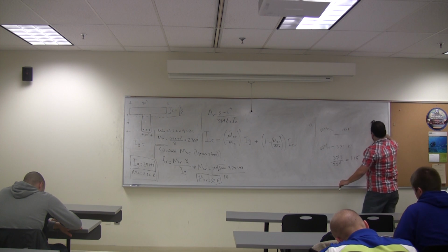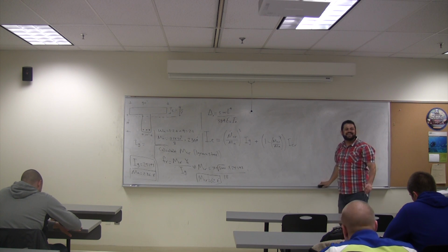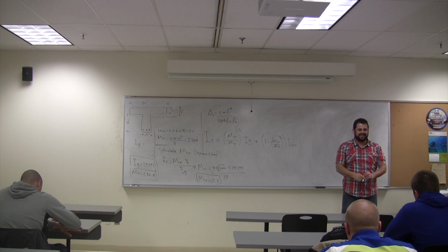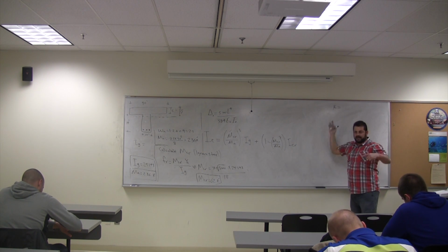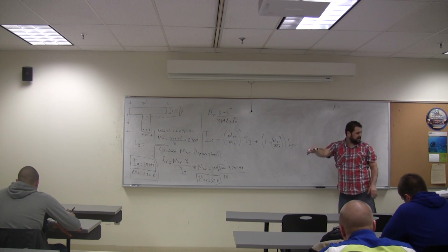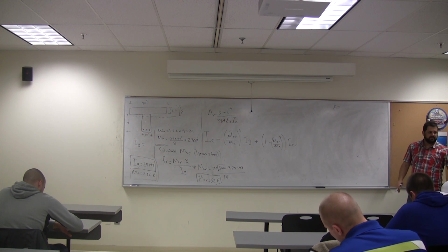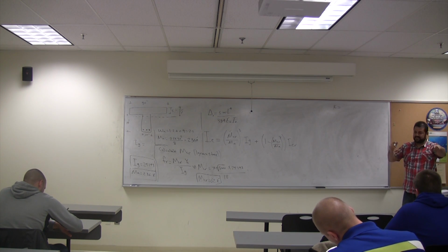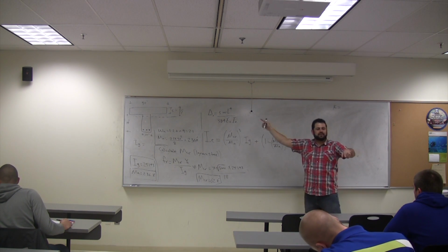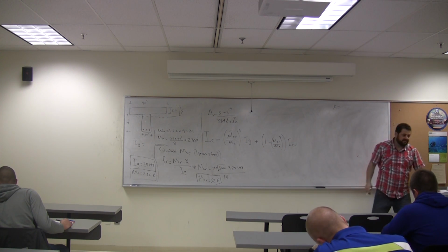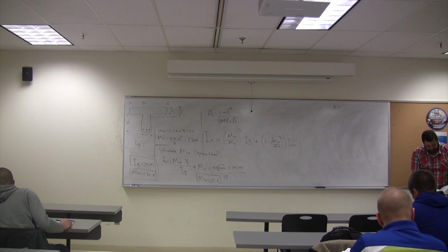Now, how do we do it? The first thing you do when I ask you I crack is what? Get K. What's K? For n equals 7. No, it's given. It's calculated for you. K and J are calculated for you guys. So what's K for F prime C equals 5,000 psi and n equals 7? Guys, forget?